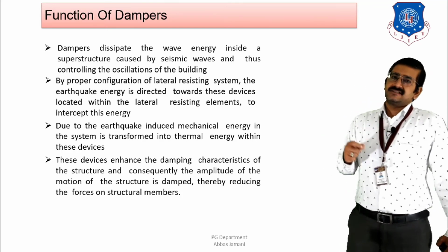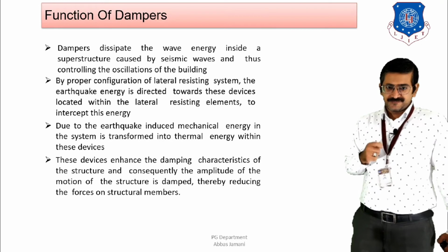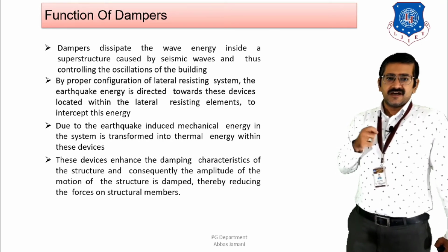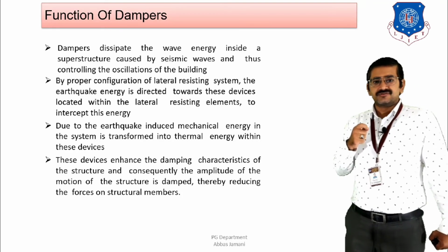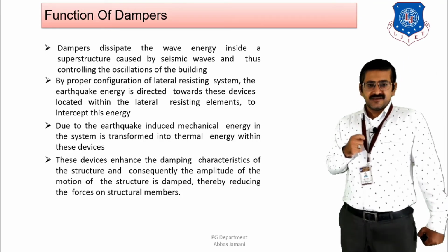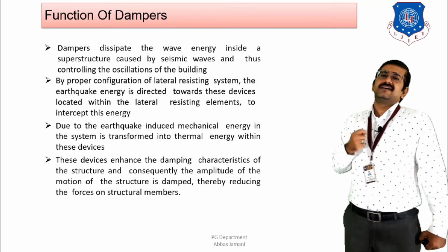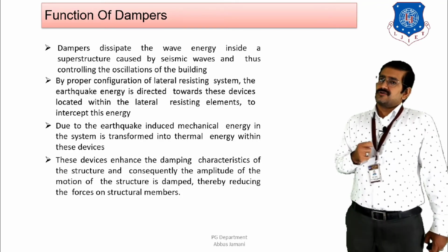At the same time, the stability in the building will also be achieved. Right? So due to the earthquake induced mechanical energy in the system, the energy in the system is transformed into thermal energy within these devices. And these devices enhance the damping characteristics of the building, and as a result of that, the amplitude of the structure will be controlled to a greater extent.